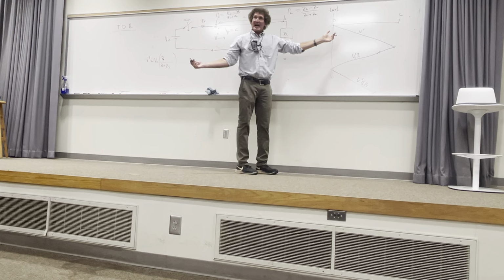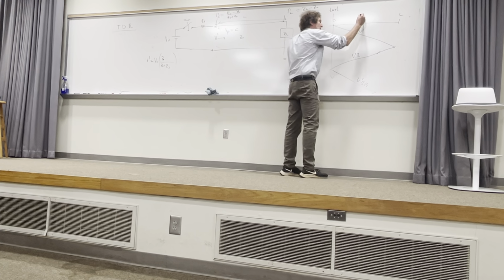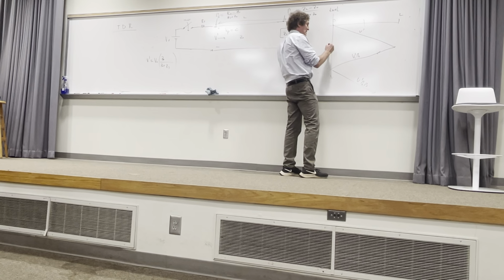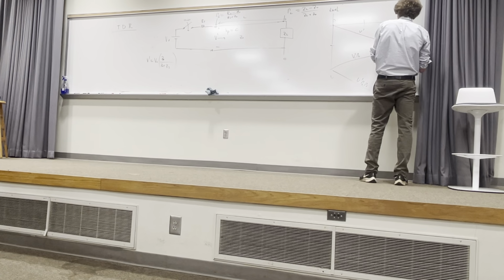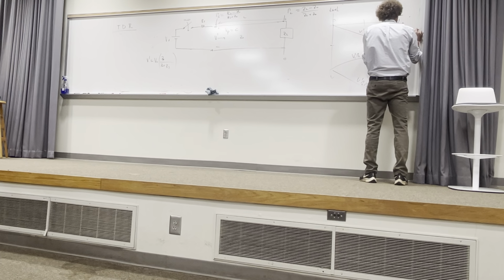Now, if I ask what voltage is at any point in the line, I pick a point here. You with me? Now, I said this is time. Well, the actual time for the pulse to go from here all the way down to the line here, this distance is going to be simply the length of the line divided by the speed of light, or the velocity of propagation on the line.